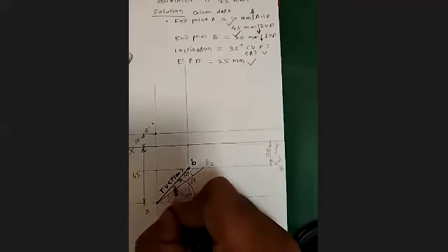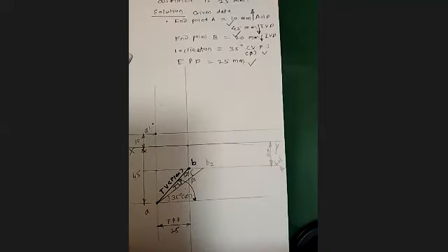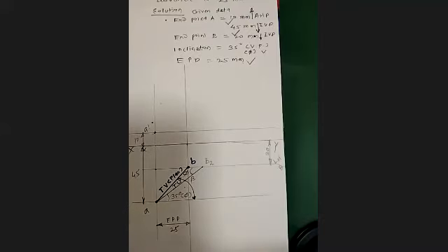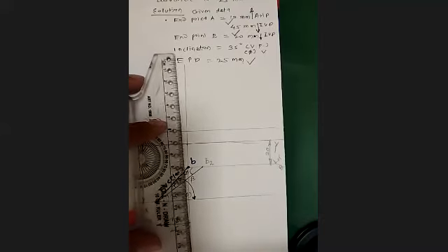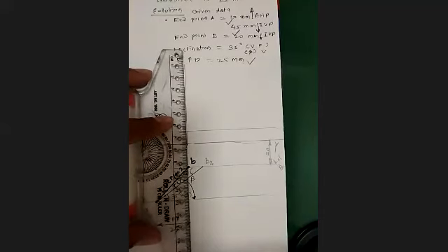So from B2, with this, you got the true length. See, this is the TL, which you have got by intersection of this locus of point B and taking 35 degree from here. What can you do next? See, the steps are quite simple. Do one thing.